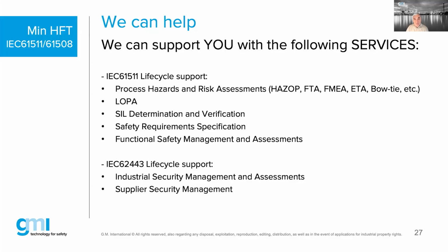As Gabriele was saying, besides training, we also do consultancy services. Lately I'm more and more dragged into the last bullet here, the functional safety management assessment. From time to time we still help people write or review safety requirement specifications, and do SIL determination and verification. It was a question of one of the delegates listening today: either to determine the SIL or to verify the SIL. These are two different concepts.